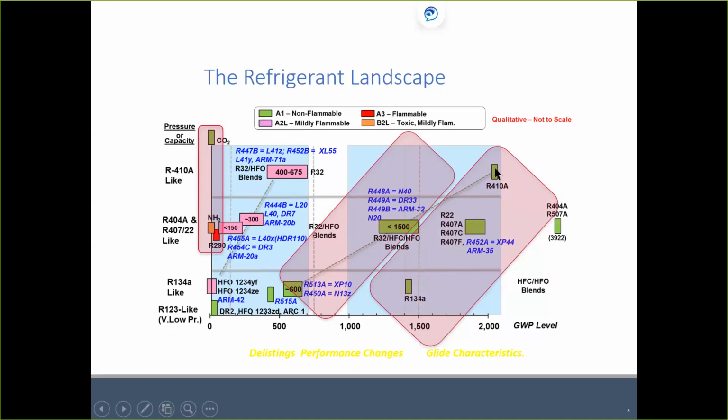When we take the other half of 410A, the R125, that's actually only in there because it's a fire deterrent. R32 was used in Asia from the very beginning. They never did adopt 410A. It went right to R32. The difference being, again, is we add that R125, you can see the global warming potential rises quite a bit. If we strip it down to its purest form, the R32, it then becomes mildly flammable, but it brings down the global warming potential significantly, okay?